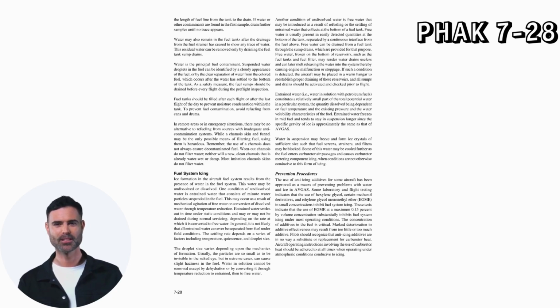Entrained water settles out in time under static conditions and may or may not be drained during normal servicing, depending on the rate at which it is converted to free water. In general, it is not likely that all entrained water can ever be separated from fuel under field conditions. The settling rate depends on a series of factors, including temperature, quiescence, and droplet size. The droplet size varies depending upon the mechanics of formation.